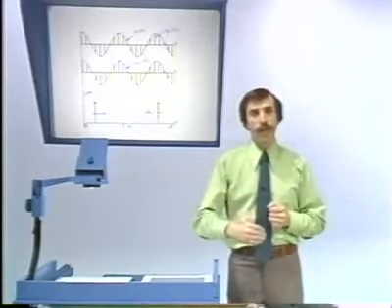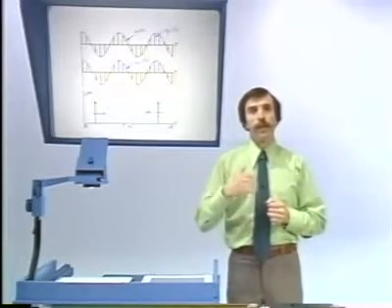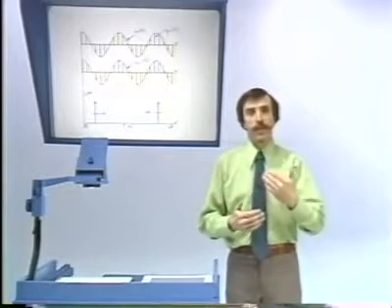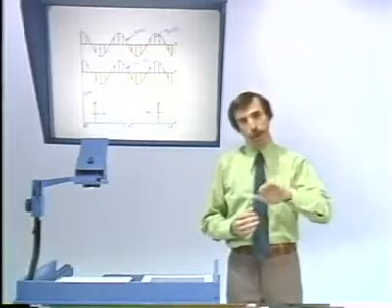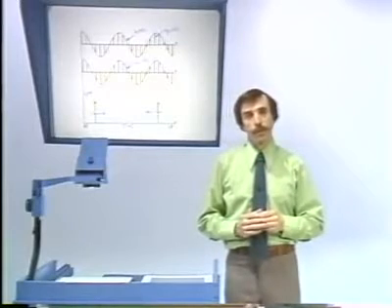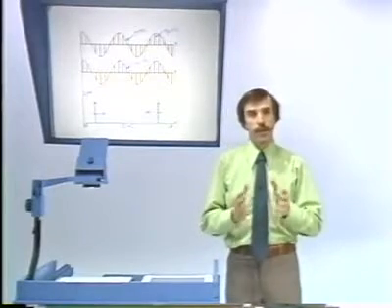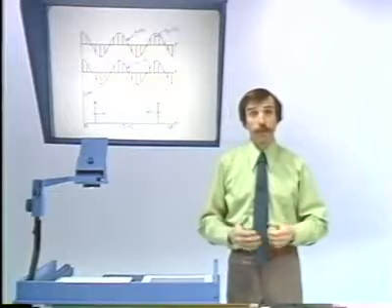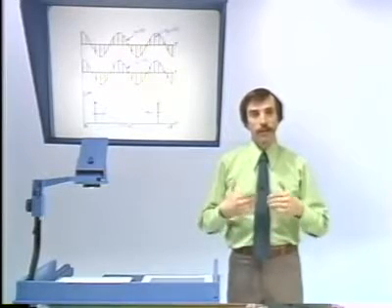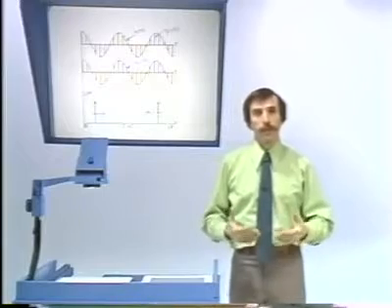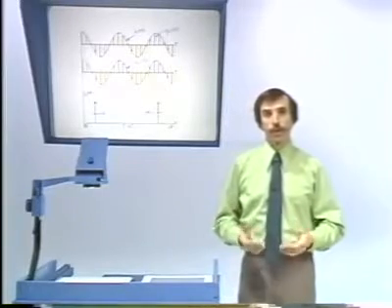That is, sampling the reconstructed signal gives a set of samples identical to the samples of the input, and it's just that the interpolation in between those samples is an interpolation consistent with the assumed bandwidth of the input based on the sampling theorem. So let's now look at that with the samples also shown along with the sinusoid.